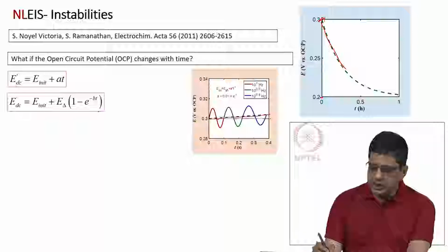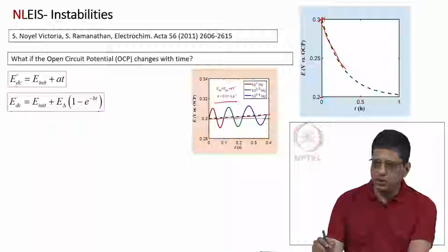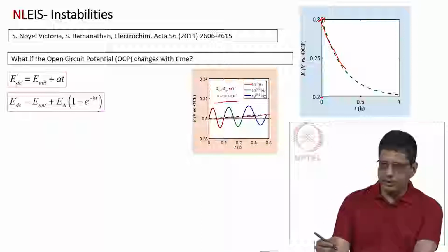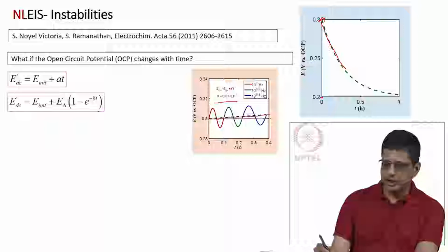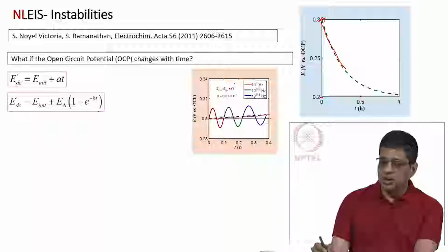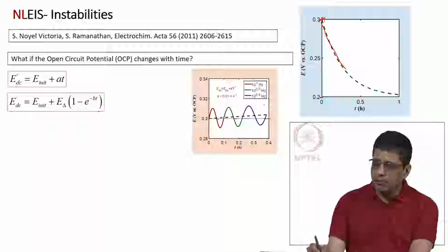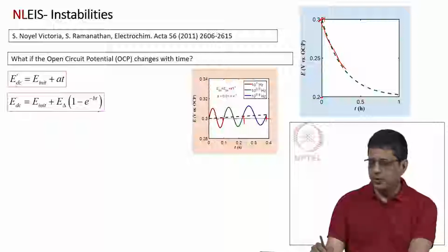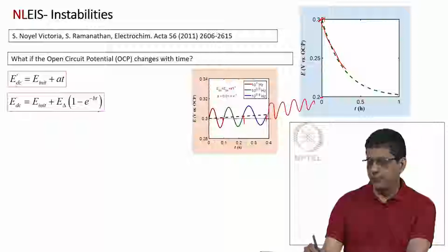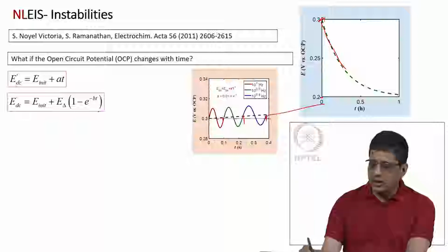So, that change is given at the rate of 0.01 volts per second, that is 10 millivolts per second, which is actually fairly large change. But I just want to show you how the potential wave will appear, and if I continue to apply lower and lower frequencies, it will continue to drift like this. So, it is not going to be a sinusoidal wave at a 0 bias or at a constant bias, the bias is changing.